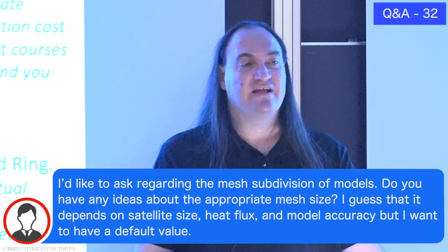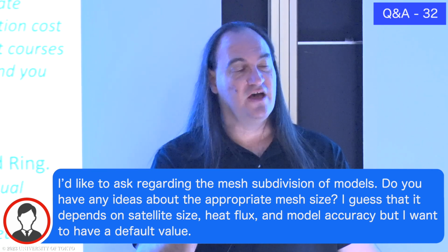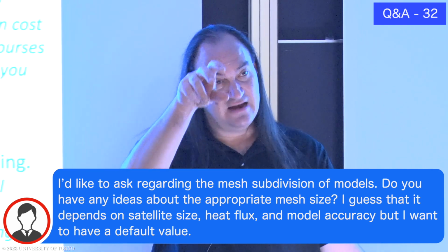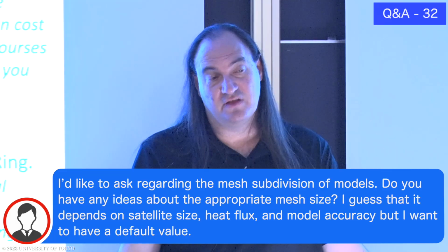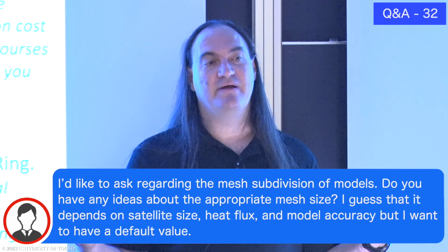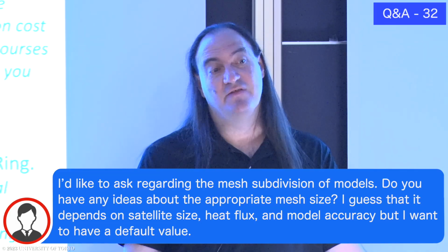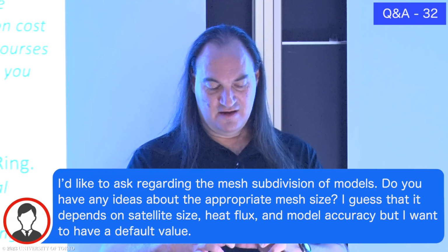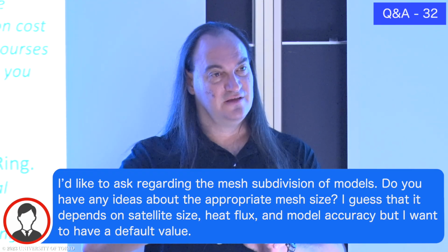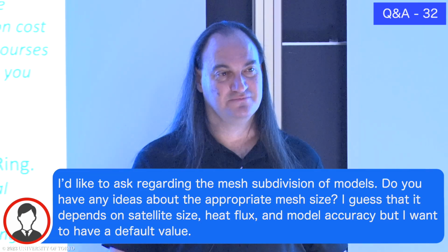But if I can say, click, click, click, click, these 4, make them 1 element, remove the other 4, then I can go and do that everywhere else, remerge the nodes, and try to go from fine to coarse. Already we have from coarse to fine to be able to do. And the other thing I'd love to be able to do is, anytime I have 2 triangular elements, let me make them 1 quad element so that I have my diagonal conductor in there.